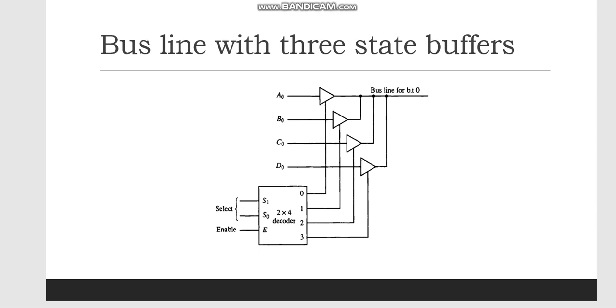The high impedance state behaves like an open circuit, which means that the output is disconnected and does not have a logic significance. Three-state gates may perform any conventional logic such as AND or NAND. However, the one most commonly used in the design of a bus system is the buffer gate.